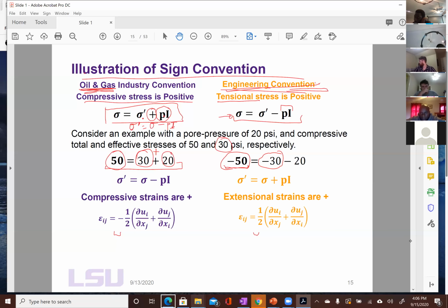If you put minus, another minus, then you double correct and it becomes positive, which is wrong. So the fact that pressure is compressive is already taken into consideration by this minus sign here for this convention. So we're just going to use pressure as it is. We don't change the sign on pressure. Pressure is pressure. It's 20 psi. Apply the 20 psi. The sign takes care of business. And now everything is in the right units.